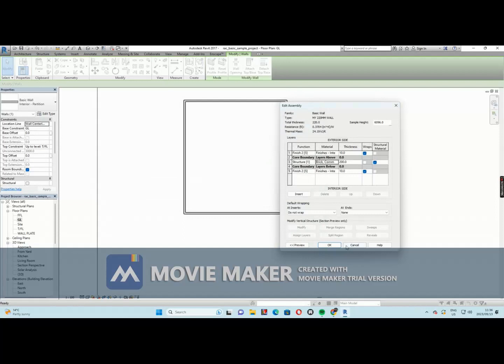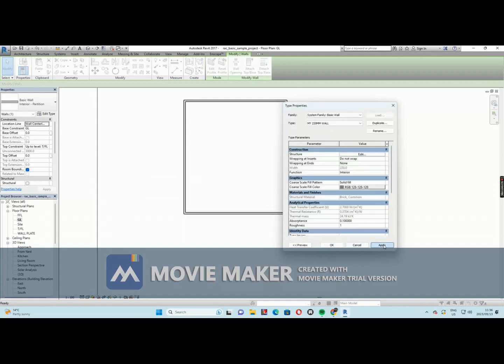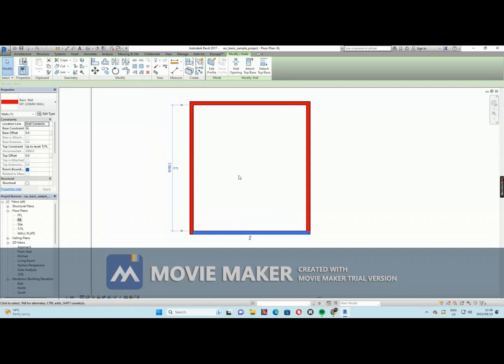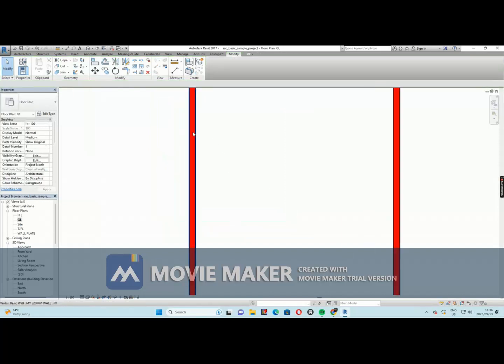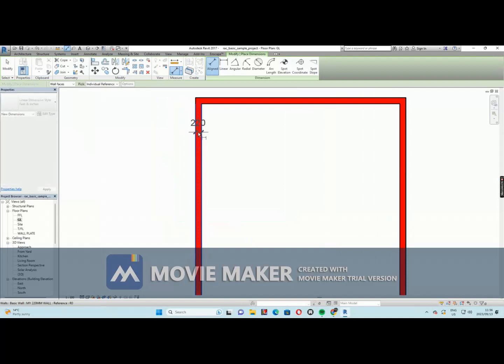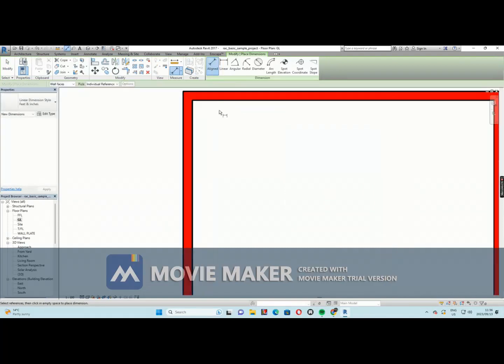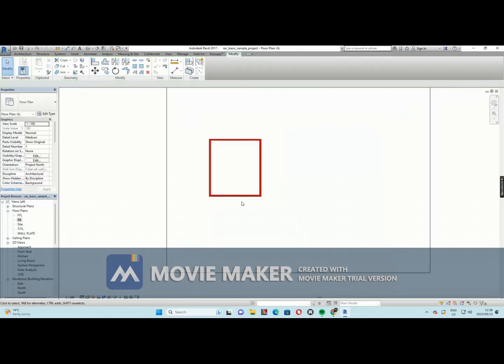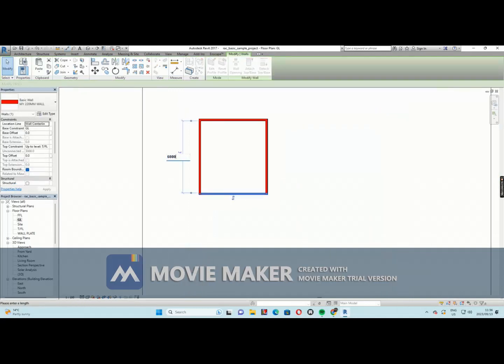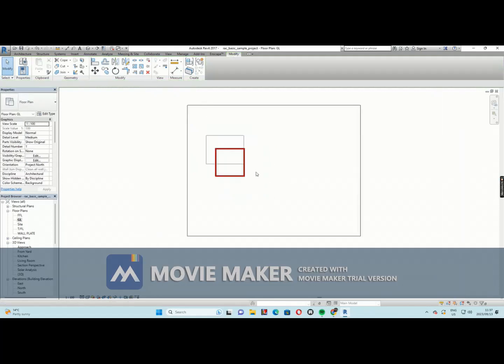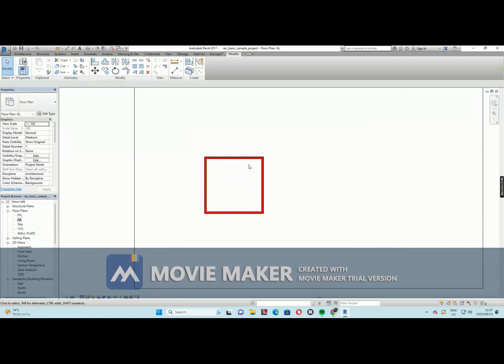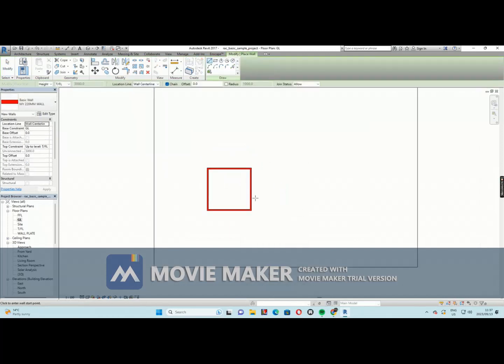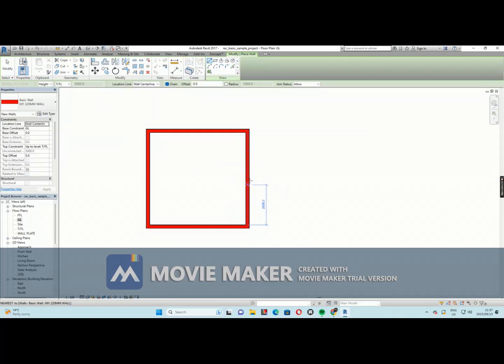You see all my walls now are solid, and if you measure it, it's 220, you see. So, right, my garage, for example, it's 6 meter, 6 by 6. You highlight, the dimension will pop up, you just edit that dimension, 6 by 6, okay. This is my garage. Let me take it down a little bit, and then let me create something. Maybe I want some stairs here, or I want a toilet here for visitors. Then I just say maybe 1.1.